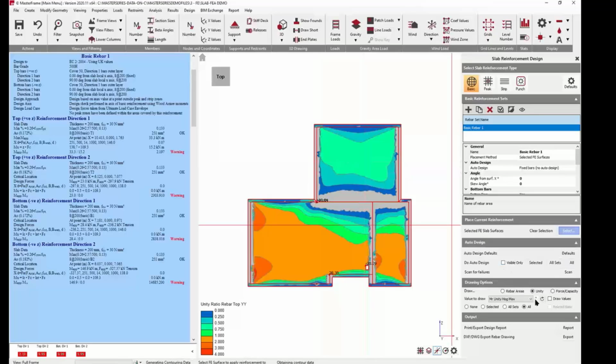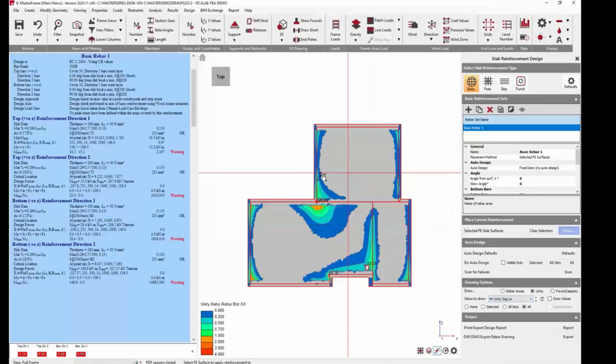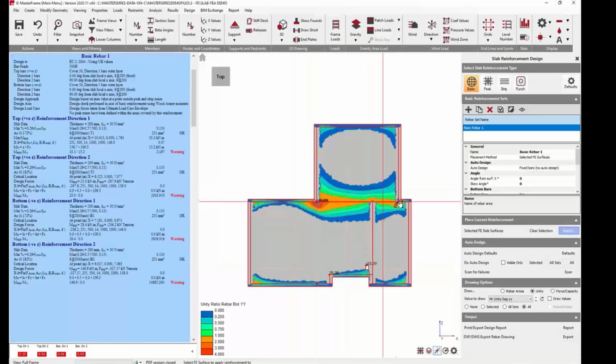When we get into it, and it's just doing them combined, the sagging. So sagging is your bottom, which is what you would think of as supports. So we can see a little bit across in this direction here and here and here, and a little bit more across this hard point where this wall was coming in and flexing across. So that's where we need to put reinforcement. So my first thought is go and change everything to A393s and then see what we need to do extra.